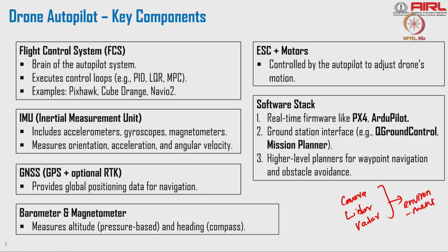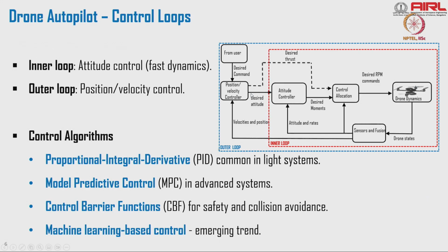So that level of autonomy comes in. In the next module, the navigation module, we'll talk about obstacle avoidance, path planning and all this. That module has to run in my brain and generate the trajectory, and the drone will follow that trajectory with the inner sensors, IMU, GPS, magnetometer. We'll use those to follow the target trajectories.